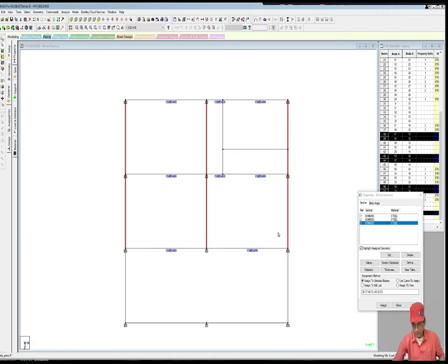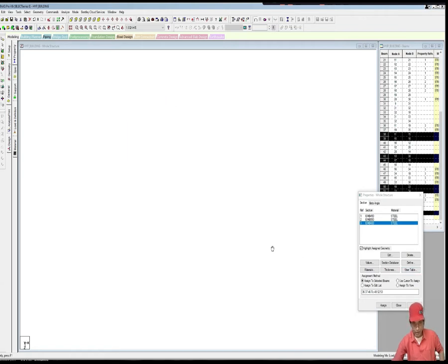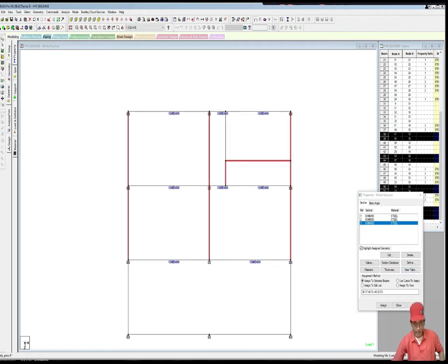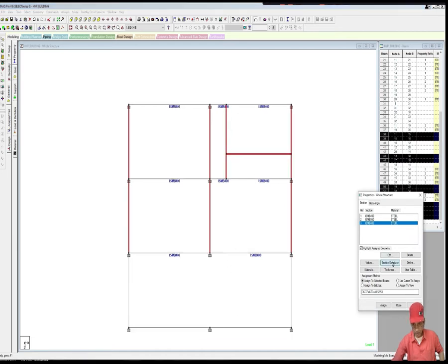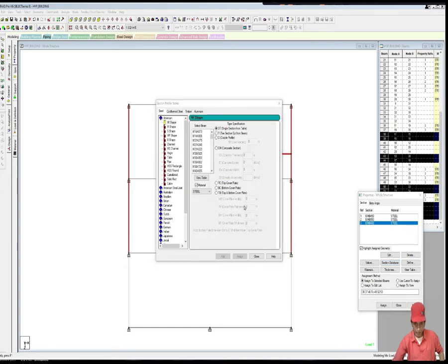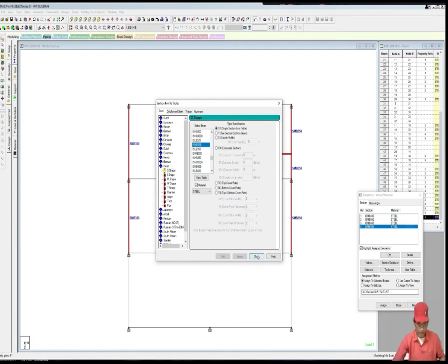It will not carry much of the dead load when you model the joist. So along with this, I assign the secondary girder also as a bit lesser section, say ISMB 350. Assign.